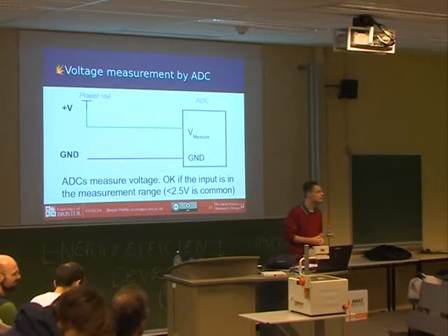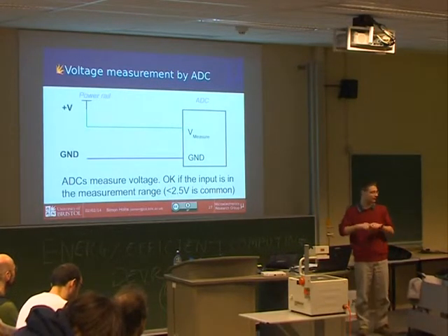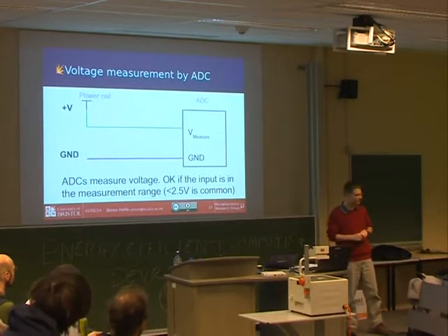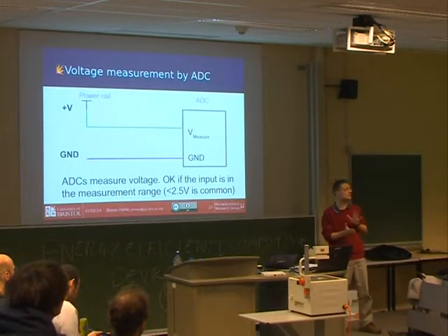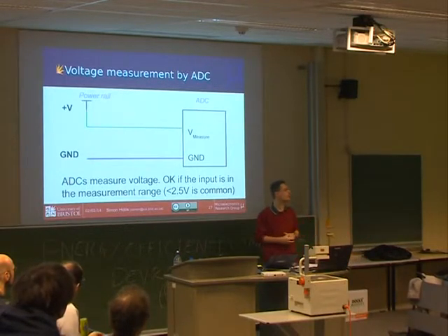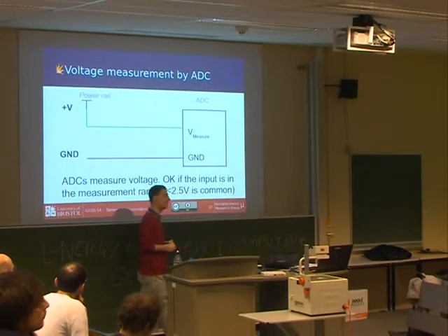Is the impedance high enough so it's not affecting the results as well? Yes, the impedance is virtually infinite. In fact, when it's measuring, it's infinite because it's disconnected internally. So they have a sample followed by conversion mechanism. So it is quite good. But yes, they're really power hungry.